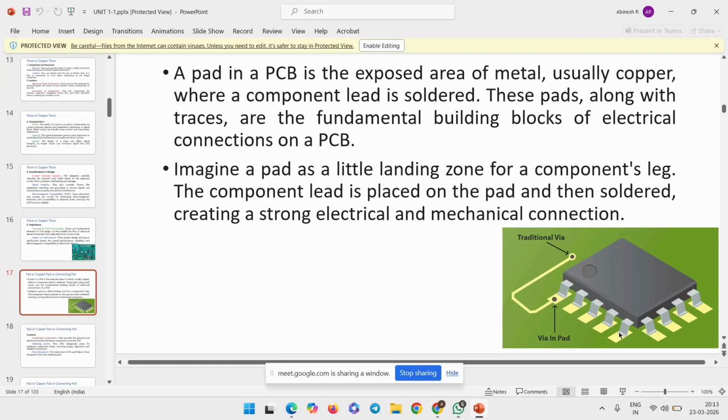First of all, guys, you can understand why we use the data sheet for component creation, because the data sheet gives the width of the pad. For example, here is the first pin. We need the pin's width and length for creating a pad, because otherwise we sometimes mismatch the shape.